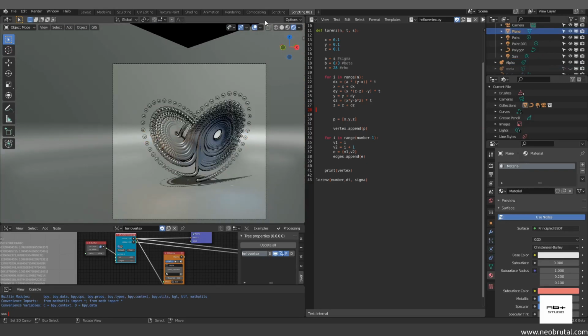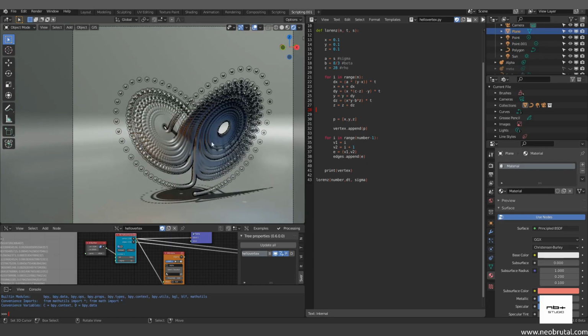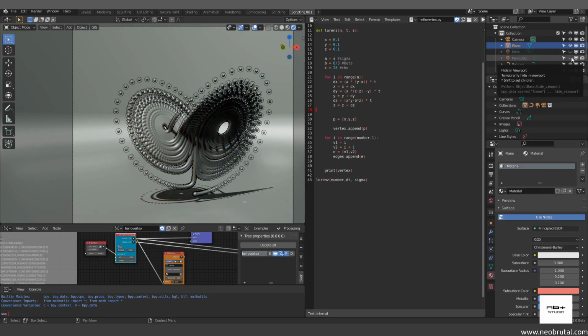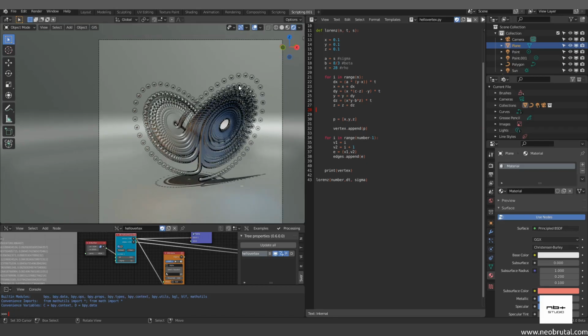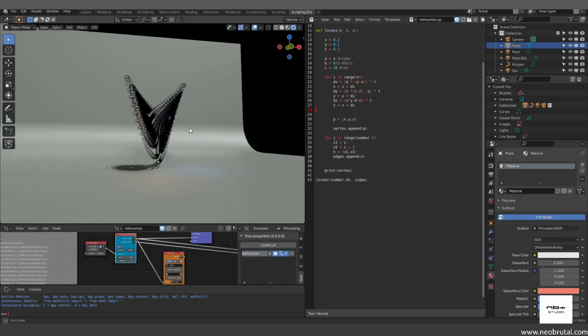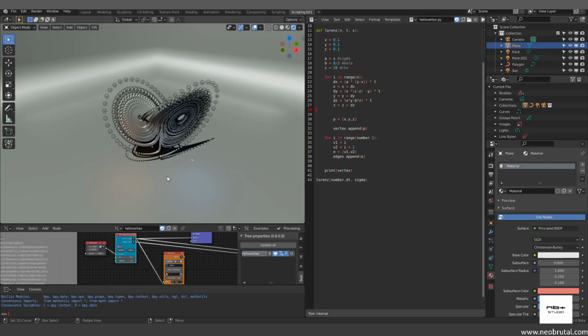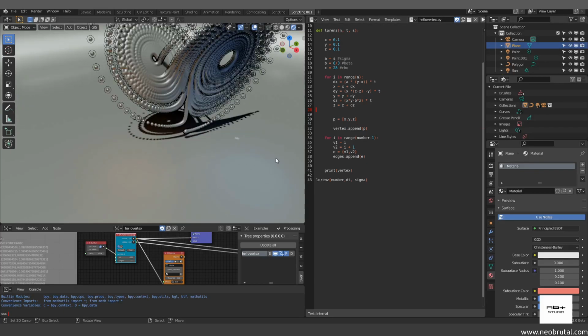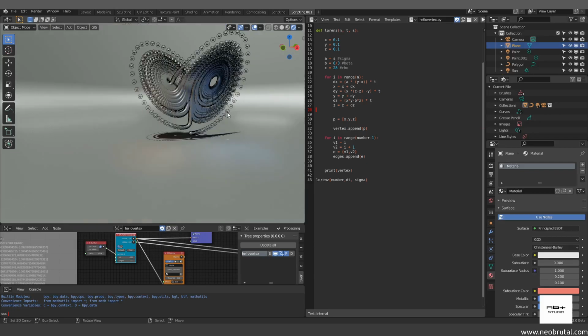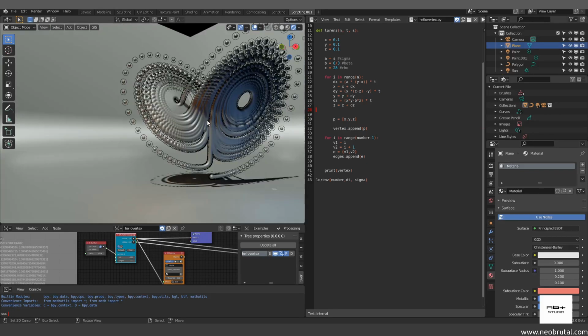Those lights that I showed you a minute ago made a huge difference on all the reflections on the dark side here, right? So if I turn off those lights, maybe you can see it. See, those lights I'm turning off make a huge difference. So get a nice angle, get some lights. And as you can tell, I have two lights. One is kind of warm and one is really cold. So this is one of the ways that you can make a really cool render from this.